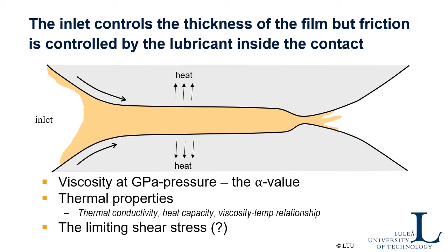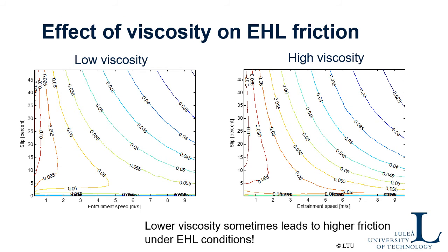So of course, if you now move the upper surface faster than the lower one, you will shear the almost solid lubricant in here, and when you shear at a high pressure, very high temperatures will occur. So you may have a hot spot somewhere here, and when the temperature goes up, the viscosity will go down, and you may have a low slip plane somewhere in the film. This is a funny effect that you can see sometimes.